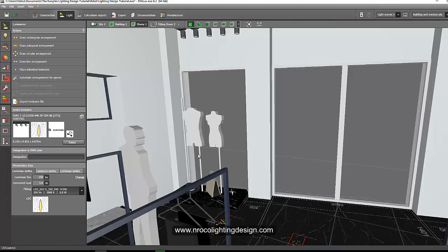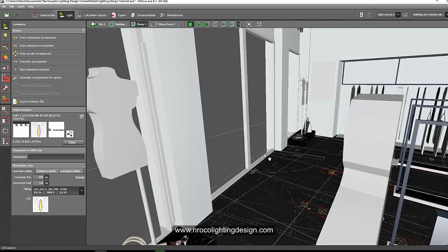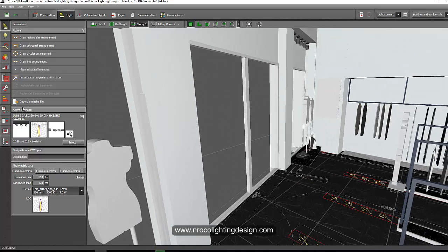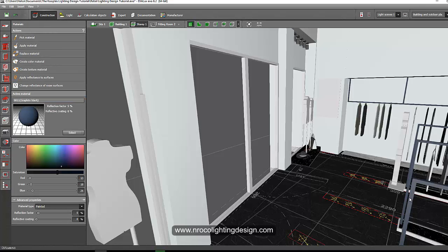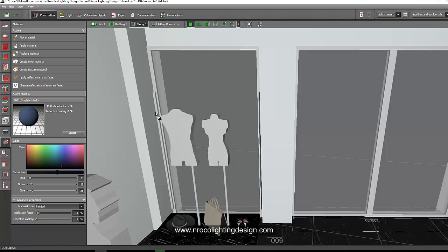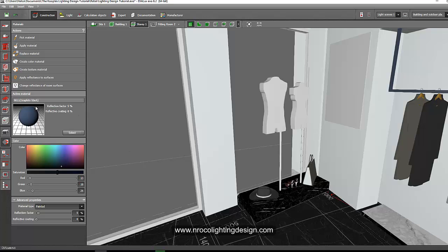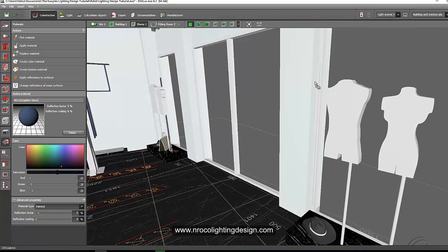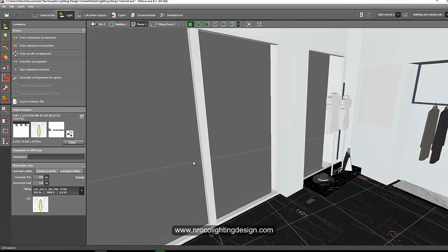So let's not save it for now. Let's paste this luminaire in our track. So since our fitting is black, we need to make sure that our track is also black. So let's go and select in the materials, pick color, use the same color here, and then paint it with black. I just picked the same color for the ceiling and handrails. I think this is, yeah, 9011. Okay, so oops, Control Z. There you go. Okay, now let's go to the luminaire and place it.